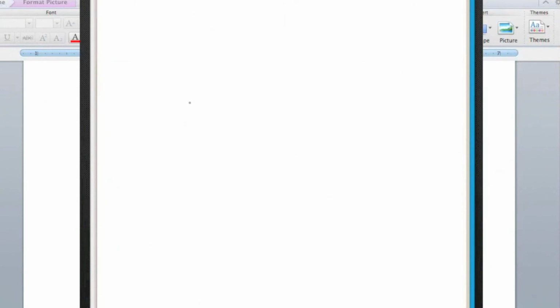Okay, so next thing to check is to make sure at this spacing that the ties can handle it, because they have a capacity. So we're going to check the tie capacity. How much load is the tie actually holding? I'll call that P sub T. It's going to be the wale spacing times the tie spacing